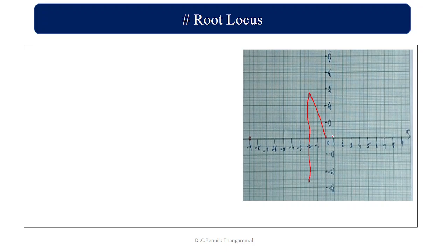Okay. So let the angle be theta 1. So this be your theta 1 and then this be your theta 2. So this is going to be the reference. So this is going to be your theta 2. So now I am just connecting the zeros to the reference pole, right? So from zeros I will be connecting to the reference complex pole, and this angle will be your theta 3. So now we have to find theta 1, theta 2 and theta 3.